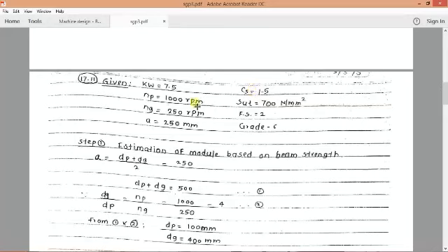So for zp equal to 20 there is y equal to 0.32. How does it come? It comes from this table that gives the values of the Lewis form factor y for a 20-degree full depth involute system, where for 20 it is 0.320 and for 30 it is 0.358. So we take a mean value from both, and we calculate y is equal to 0.34.